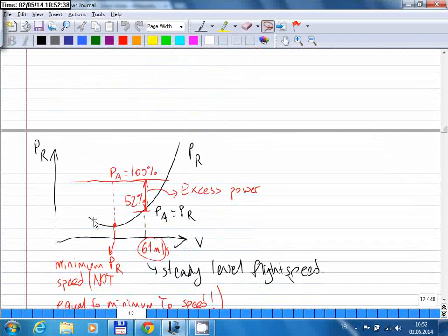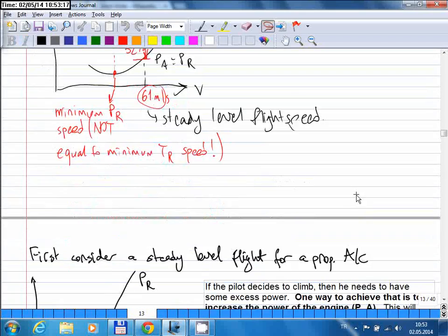So the power required curve looks something like this. And normally in a steady level flight, the power produced by the engine should be equal to the power of the flight. So we should be flying at an intersection point between the available power and the required power. But if the available power is more than the required power, something like this, for example, this is your flight speed, and your engine produces this much power, whereas the flight requires this much power. So this difference here gives you the excess power. Okay, so if you just calculate this number and then divide it by the weight of the aircraft, you can directly calculate the vertical speed of your aircraft.